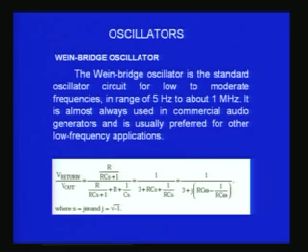When you want a variable frequency oscillator, everybody wants a variable frequency oscillator. You just now saw a function generator which I used, where I was turning a knob and the frequency was changing. If you want to do that in the RC phase shift network, you have 3 resistors and 3 capacitors. You have to adjust all of them, either equally or differently.